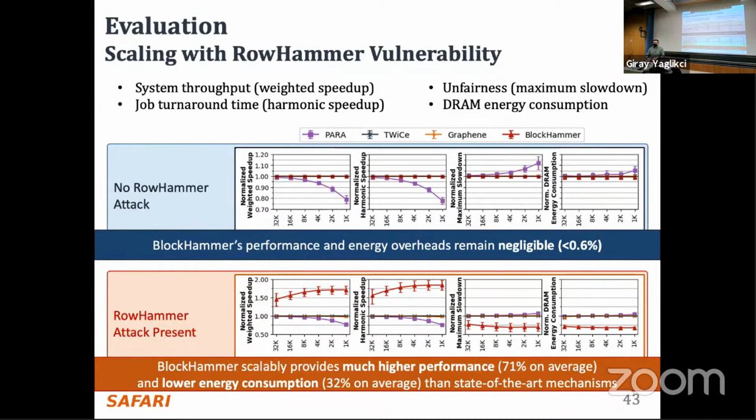Yeah, but in my experience, I didn't see them reach up to the RowHammer threshold, because for RowHammer you need to reach some large hammer count in a very short amount of time. But in this kind of behavior that I explained, row-level temporal locality, usually you see this row being activated in, I don't know, the next microsecond or something like that. I don't know if anybody remembers from the audience, maybe.